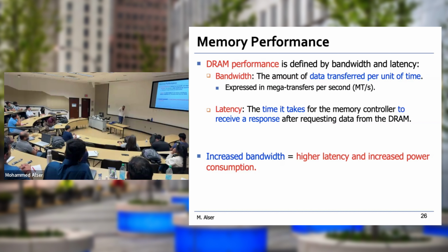But also if I increase the number of rows in the chip to fit more data, to increase the capacity, I also need to change the decoder to decode the row where I need to fetch the data. But not only that, I also need to increase the size of the row amplifier or the row buffer, the sense amplifier, right? Increasing all those hardware would require more time to fetch more data, right? And also it's expensive, reducing energy and so on.